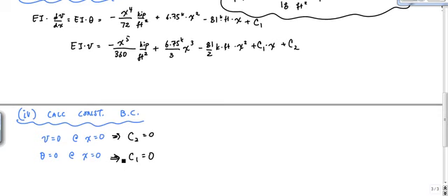Awesome, right? And then to find the maximums, I would plug in the numbers for EI that were given. To find v max and theta max, just substitute x equals 9 feet into the equations, and just make sure you don't mess up your units. And that's it.